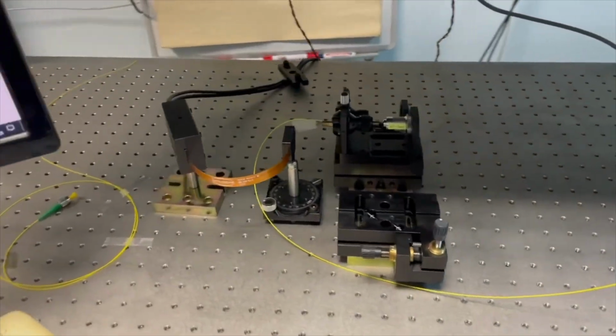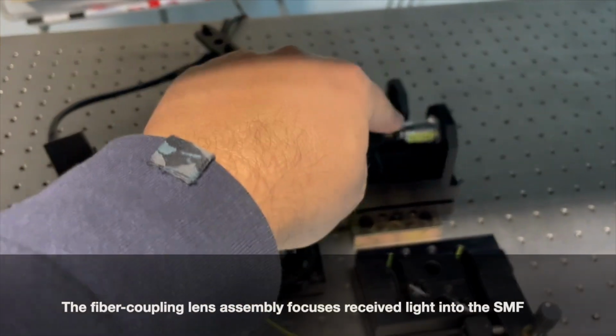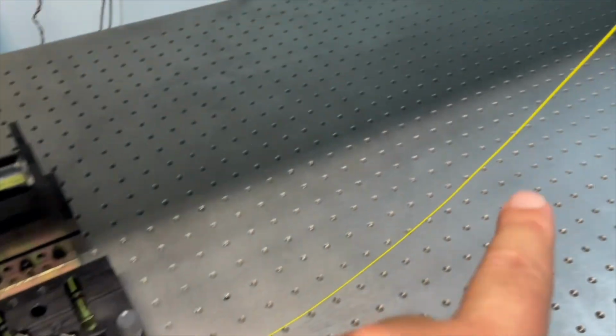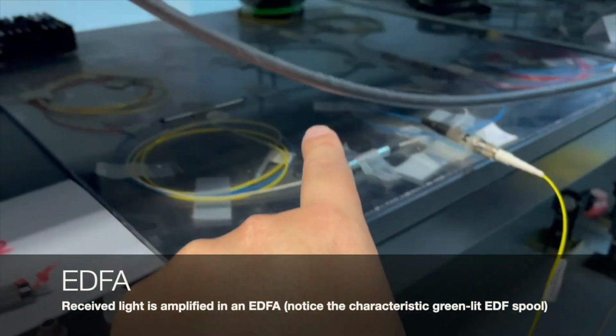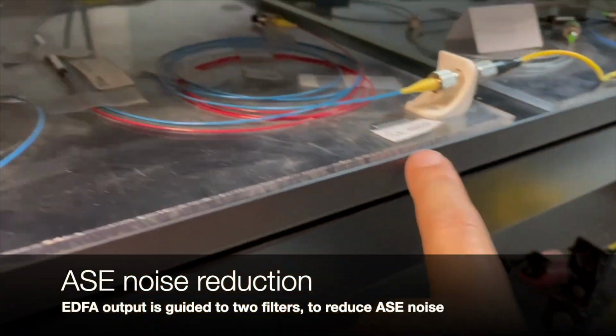The SLM is configured as a flat mirror, slightly rotated. The fiber coupling lens assembly focuses received light into the SMF. Received light is amplified in an EDFA, notice the characteristic green-lit EDF spool.